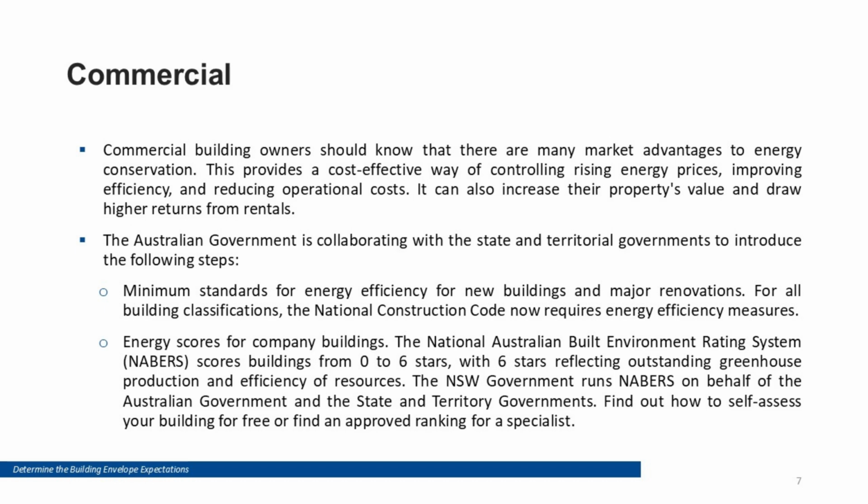Commercial. In commercial buildings, energy efficiency is strongly tied to operating cost and ongoing performance. Expectations usually include efficient glazing, controlled air leakage, well-integrated HVAC, and strong maintenance and commissioning practices. Systems like NABERS help measure and improve operational outcomes after construction.